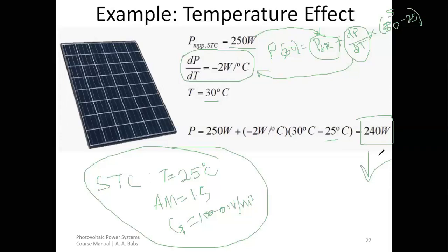So your design characteristics have to be top notch and on point. At standard test conditions, T equal to 25 degrees Celsius. That is constant, all right? At NOCT, nominal operating cell temperature, I'm going to mention that later, T is equal to 20 degrees Celsius. Our G would be equal to 800 watts per square meter, all right?